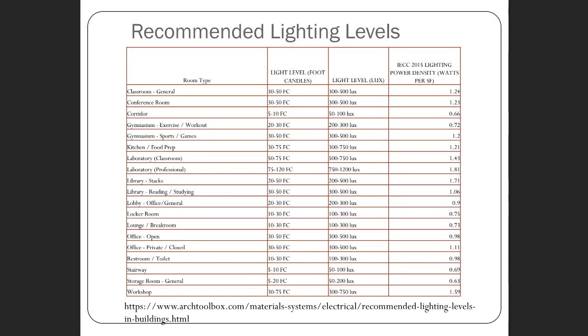And oh, by the way, we also have to pay attention to the lighting power density, watts per square foot. So not only does your lighting designer have to make sure that we have proper illumination, we also now have to do it within a certain lighting budget, right? So you or your lighting designer has to balance both of those things, providing the right level of illumination and doing it in an energy efficient manner.